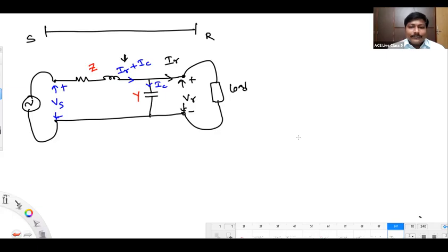Okay, next thing. See, if the charging current is negligibly small, very simple analysis, don't complicate. The charging current is negligibly small, then obviously this IR plus IC what we have now, you can write approximately as IR.